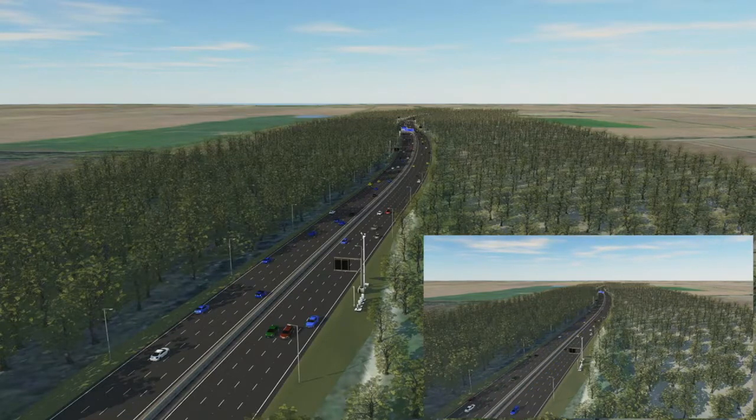The question is on the signboards. You haven't shown any text on that, but when we actually do the signboard, the one we are seeing in InfraWorks, is it a 3D solid, or how are you importing it? Again, it could be a 3D solid, but I think that could be a 3D face, a 3D mesh again. So rather than the sign and the text being flush, the text actually has a height that's a mesh, and InfraWorks reads that mesh and reads the colours, and when it brings it in, it applies the same textures to it as you would see when you click a realistic view in the software.